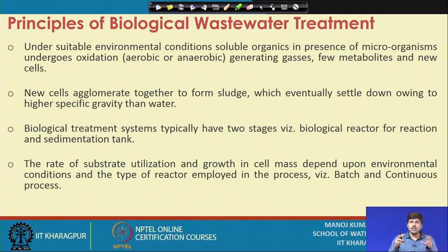We provide the organic matter, typically soluble organic matter, and there are microorganisms present. The organic matter undergoes microbial oxidation, whether in an aerobic or anaerobic system, and through the process it creates a few metabolites, new cell mass or sludge, as we refer to it, and some gases.